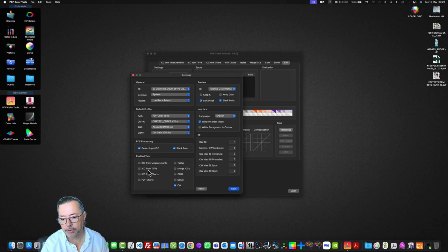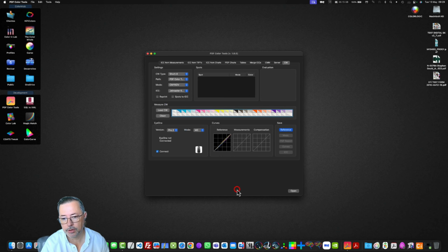On the other hand, now that I'm here in the settings, I can review the delta E's that by default are 3, but I can customize the delta E differences, tolerances that are going to be used for maximum primaries, spot averages, and so on. We will look at this later on. So I'm going to save the settings. So now I can just work with the control wedge.